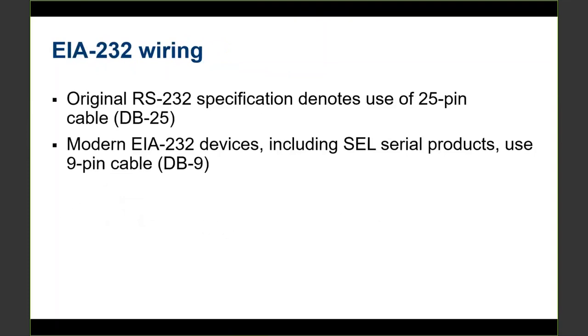So the original RS-232 specification denotes the use of this 25-pin cable. Where you'll see that in substations, generally speaking, I see those on modems. Usually I'll see a 25-pin port on a modem. I'll still see that from time to time. But that's pretty rare on SEL devices.